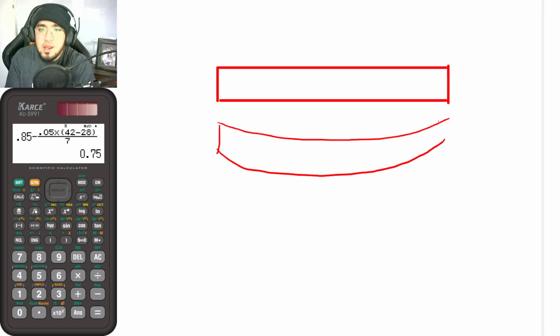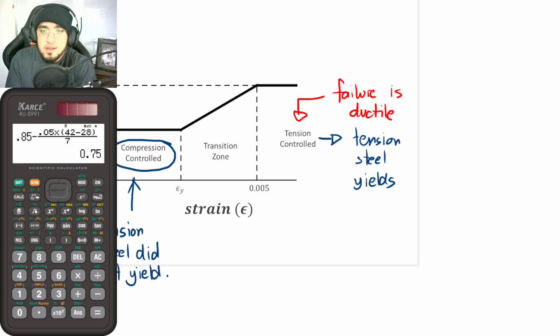You would see that the tension side would crack. So the tension side cracks, but it would be ductile in a way that it would slowly fail. It is not actually abrupt. So once again, this is ductile. It is slower in nature, in failing.